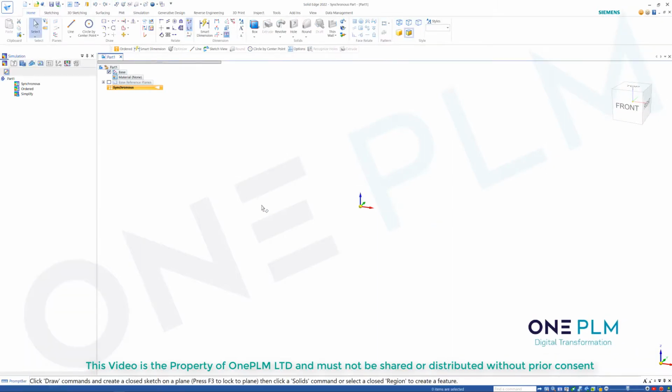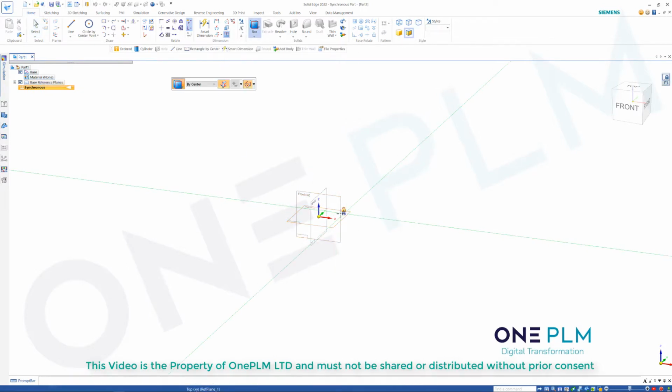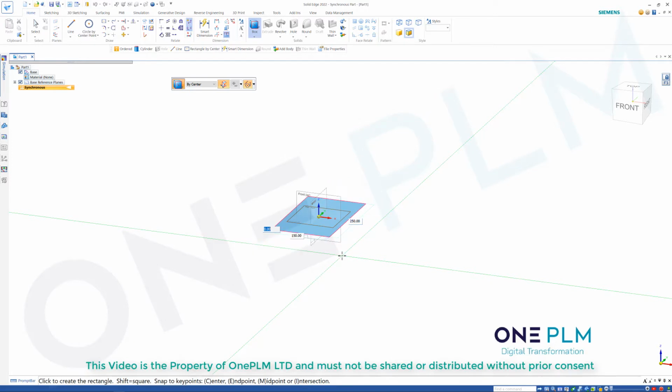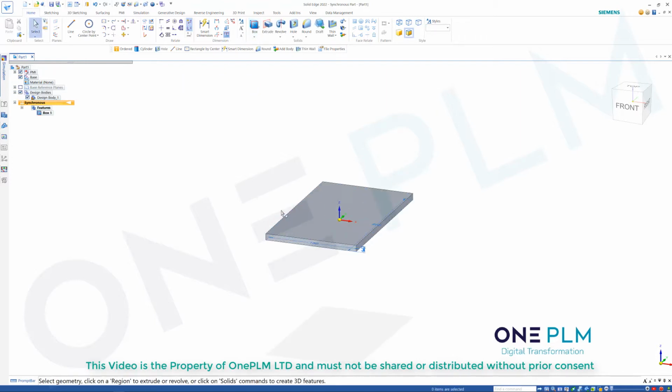Initially we're going to start in synchronous. Simulation training, so let's get rid of that. And we're going to start with a box. For this I'm going to F3 on that plane. I'm going to start on the center. Let's go 150 by 250. Tap the shift key because we want to build this upwards, and let's go 10mm on that plate.